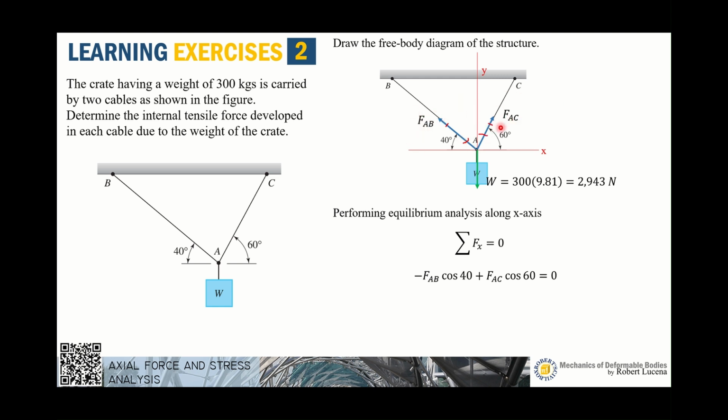FAB and FAC. It's not necessarily that you have four unknowns because of two components for FAB and two components for FAC. It's not like that. You only have two forces, so you have only two unknowns. As you can see, in the x component the only unknown is FAB. You don't write FABX or FACX. It's more convenient to express it in FAB.